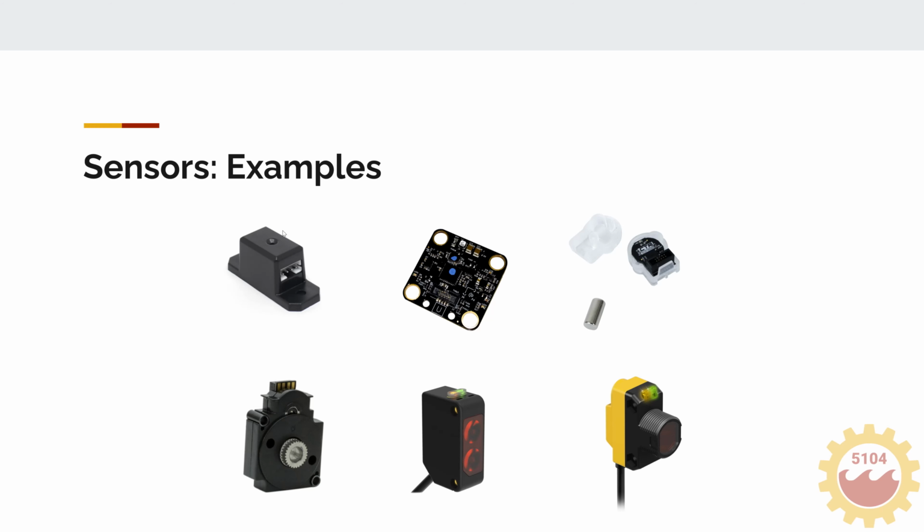The nice thing about this sensor is this blue LED turns on when the magnet's in range. So that's super useful. Let's say we have a limit switch at the bottom of an elevator, and I want to make sure the limit switch is working before the match. I just look down and I see a blue LED, and I know it's wired correctly. You don't have to use a voltmeter or anything. You just automatically know, okay, it's working.